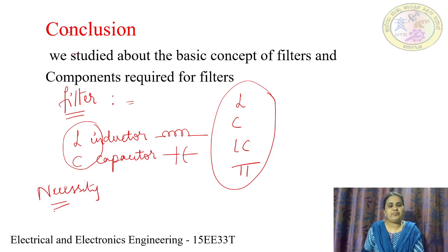Also, the unwanted noise resembles the type of the rectifier. Hence an electronic circuit doesn't respond properly to the load. And also the DC output is expected to be a voltage which is constant with respect to time. So all these requirements tell us that we compulsorily require a filter.